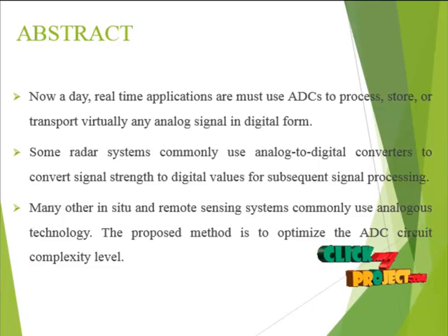The maximum sampling rate required for sensor applications is usually only a few megasamples per second, which is smaller than the typical sampling rate at which a pipeline ADC shows its best conversion efficiency. So for any type of sensor, we are going to convert the signal from analog to digital in real time. We propose the pipeline ADC as a potential candidate for ultra low power applications.